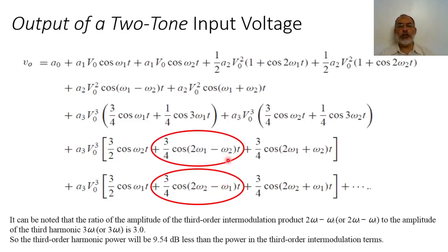These two terms actually are quite close to the values of ω1 and ω2. So effectively, if I have an input with ω1 and another input of ω2, and these two inputs are simultaneously input at the input port of the nonlinear device or circuit, we have output ω1, we have output ω2, we have output 2ω1 − ω2, and we have an output 2ω2 − ω1.